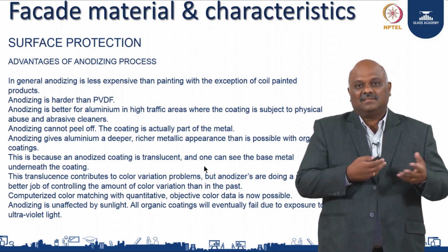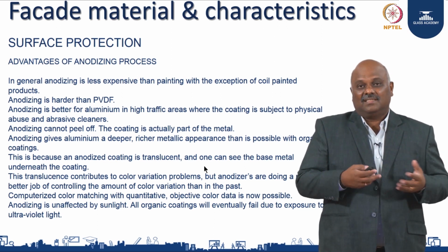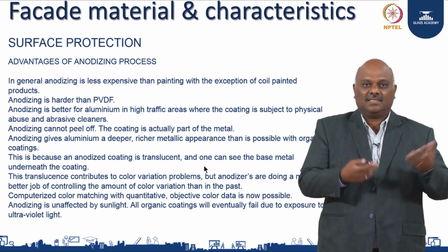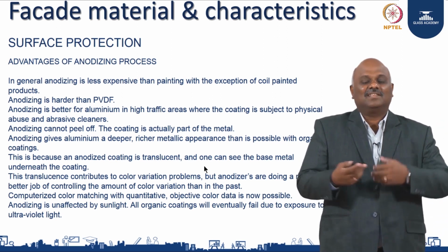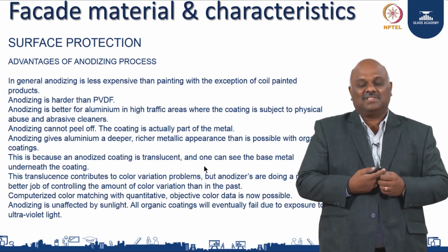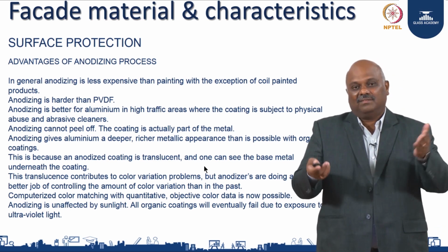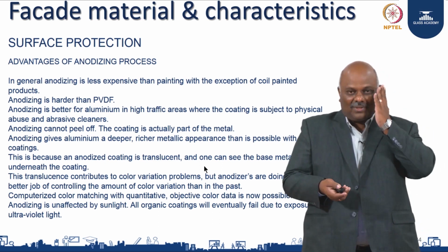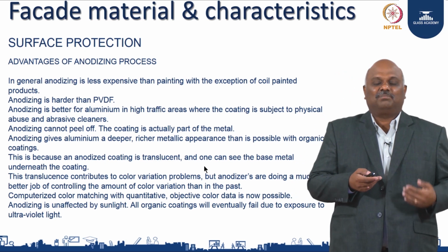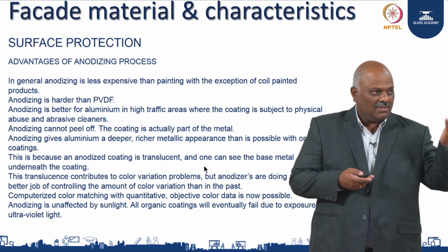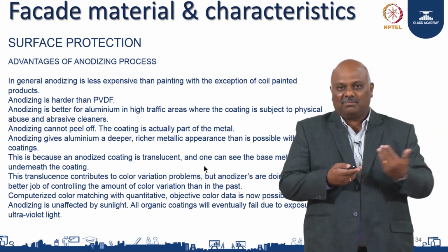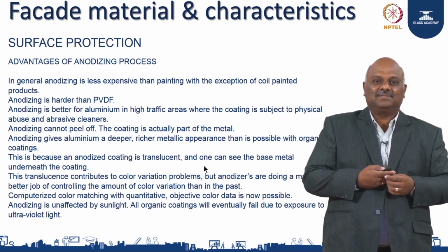So, there are plus and minus. Anodic, yes, it's harder, but there is no fixation. If you have a scratch or a dent, there is no touch-up work available unless you do something superficial. But when you go for PVDF, it's a coating, like the makeup we do. You apply a paint that is fixable. Even if you have a dent or a scratch, you putty it and repair it like you do with a car, with proper quality control in place.